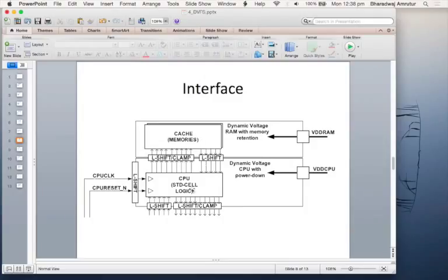So that is why, because you maybe, for example, have the memory, and you want to retain the state of the memory. So you might disconnect this but keep that. In which case you have power available already, and you have to use that VDD from the other side. The VDD of the receiving logic domain is what you should actually use.